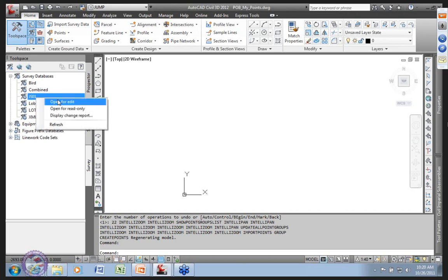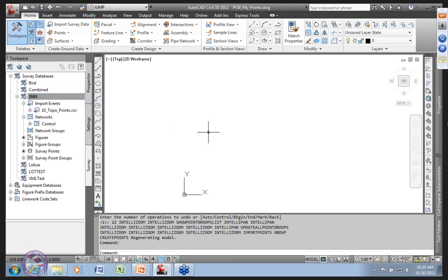I'm going to open one of these databases. One of the little tricks over here in Survey, another thing they don't tell you, is you can have a separate working folder from your project working folder where your data shortcuts are stored. They don't have to be in the same place, and you have to make sure you're pointing at the right place.